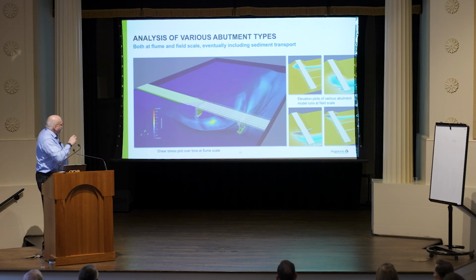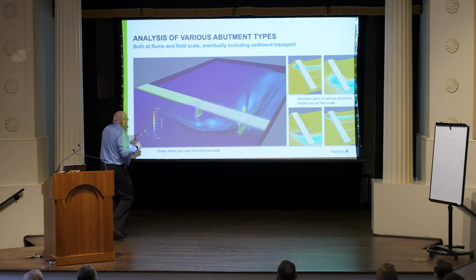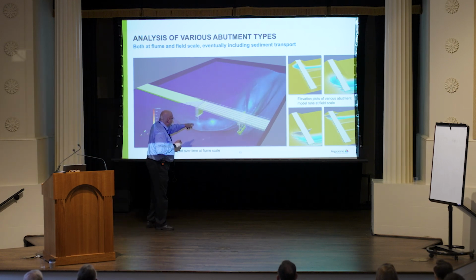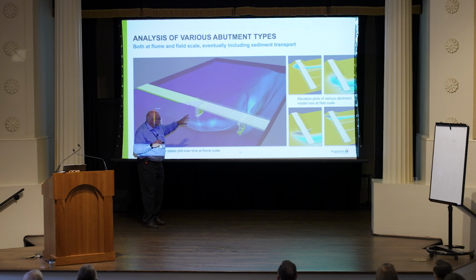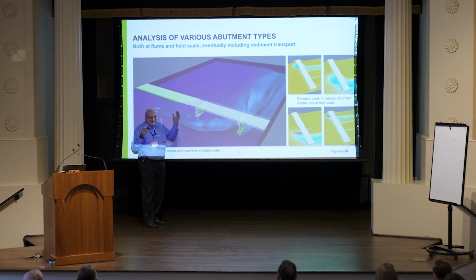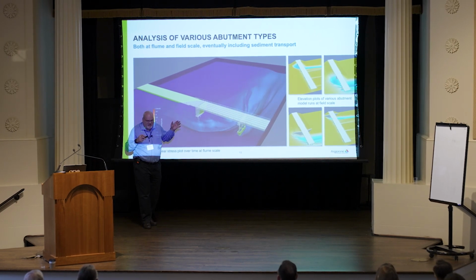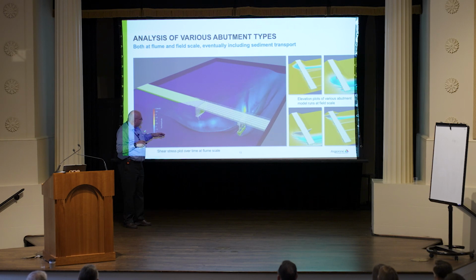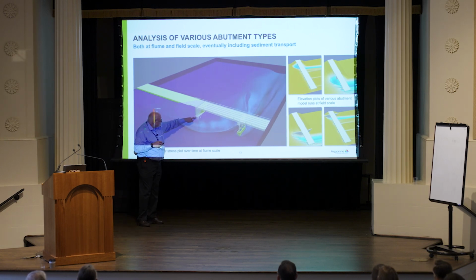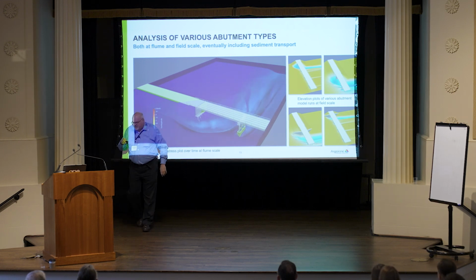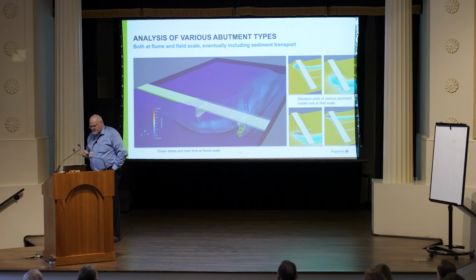But what you don't have here at all is the deposition of sediment, right? And what you get as a result is a scour hole that's probably very unrealistic, right? Because the stuff that gets picked up is dissolved like salt into the water, right? For a first shot, that was good enough, right? And it really shows how you can do this easily and expose, for example, all the piles under the pile caps. I mean, you can throw very, very complex bridge geometries at the problem.